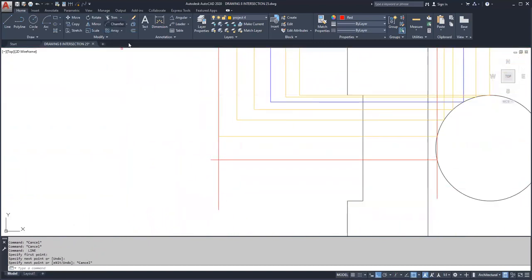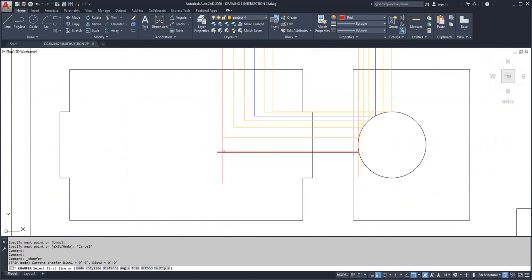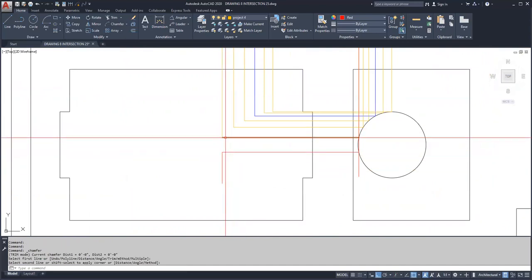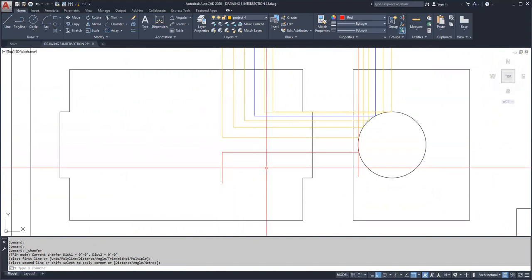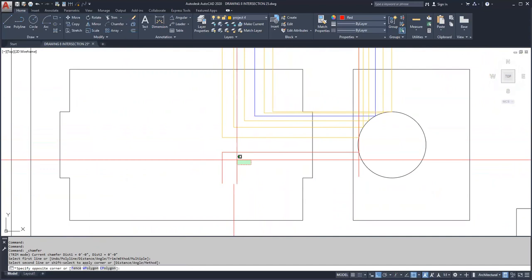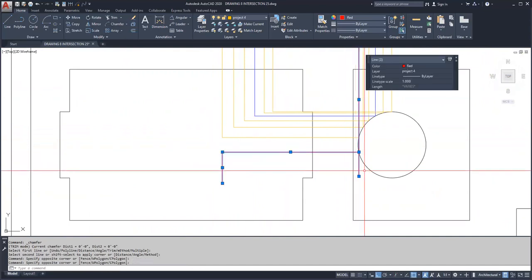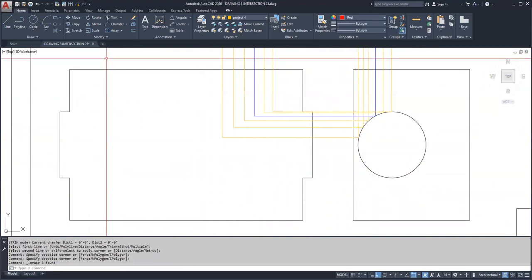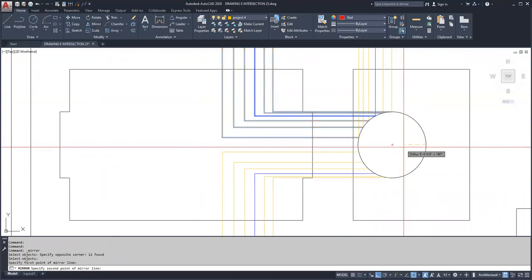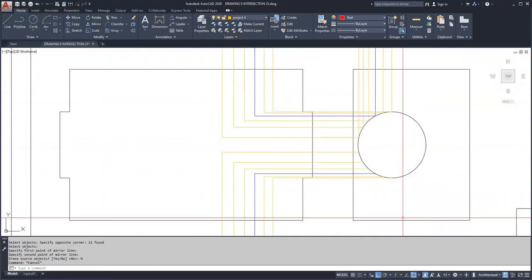So what you're going to be doing is actually creating intersections down here as well, but you're really replicating the same one, mirrored off the center. So instead of me going through that whole process in this video, what I'm going to do is just take these objects and mirror them through the magic of AutoCAD.